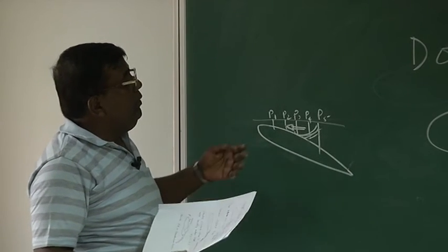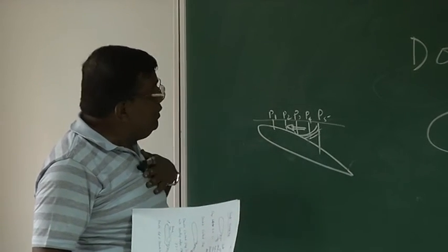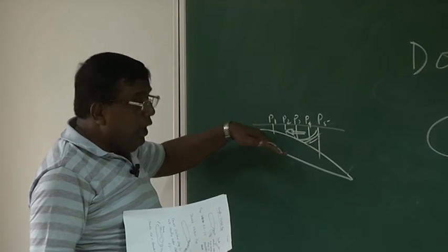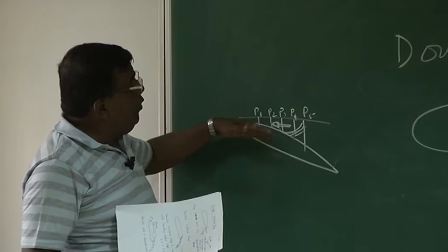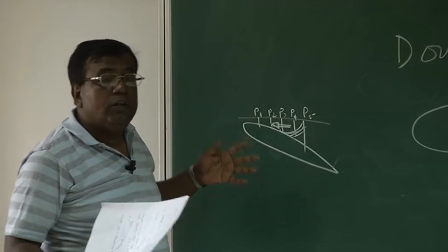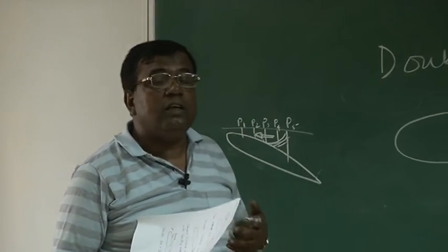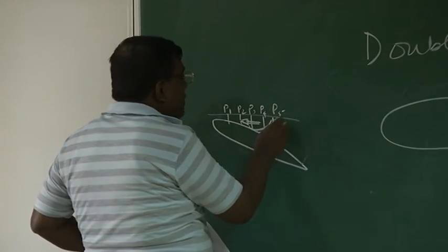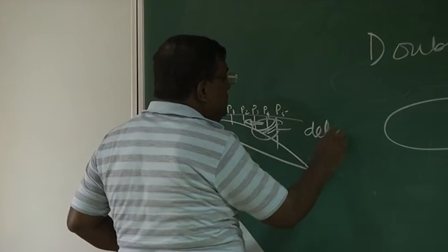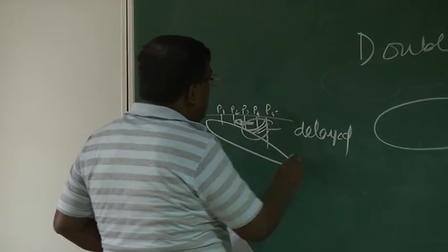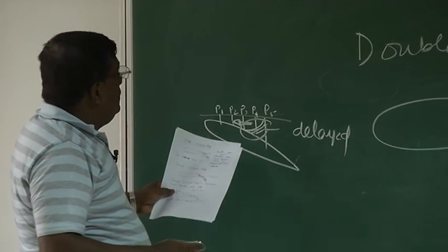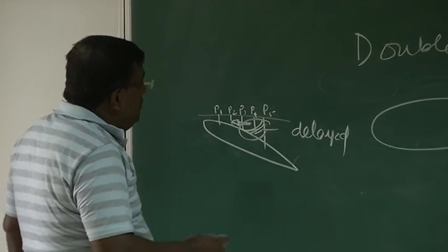In the language of flight mechanics, that means I will not be able to use beyond the angle where flow separation starts. So the flight mechanics man will ask a question: do I have a mechanism to ensure that this separation is delayed, so that I can use a further angle of the flap? By simple common sense, what does it mean?